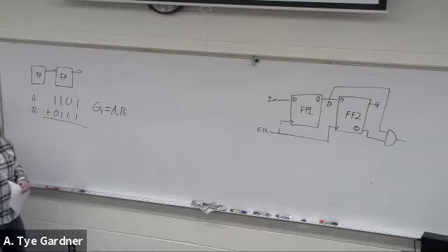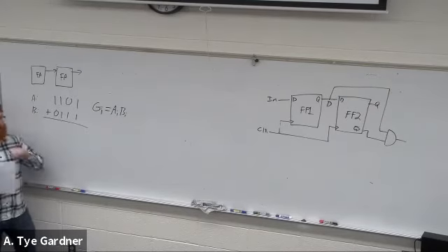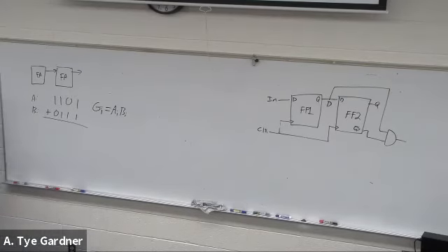Is it going to generate me a new carry? So any given index is A at I and B at I. If both are true, I know I'm going to make a carry in that column, right? So with one AND gate, I can already start saying I'm going to make a carry.